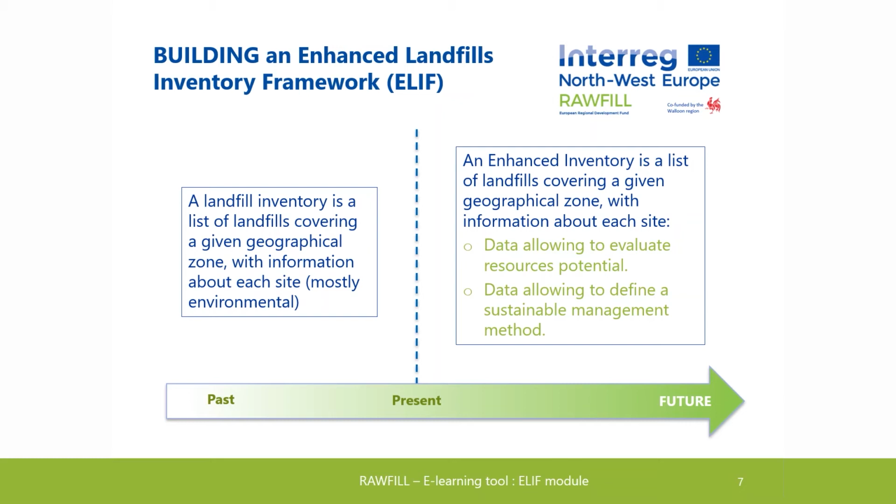The enhanced landfill inventory developed by the RAWFILL project includes, in addition to information from a conventional inventory, all suitable data for assessing the resource potential of the listed landfills. The word framework is used because ELIF is a database structure. It does not contain any data by itself. It should be filled by the inventory's users. The landfill mining option is not suitable for all landfills and mostly depends on the development of the mining market, which is related to the price of materials, energy, and land.